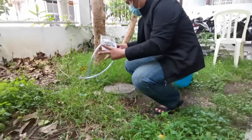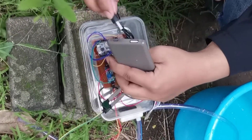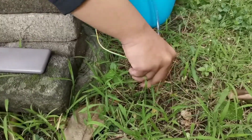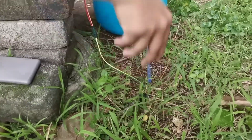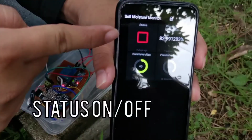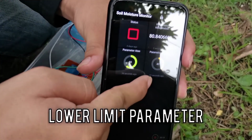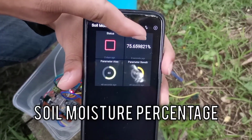So, we put it here and we use a power bank for the power supply. Plant the sensor into the ground. Next, we use the MQTT app. We have the on/off status, upper limit parameter, lower limit parameter, and soil moisture percentage for monitoring.